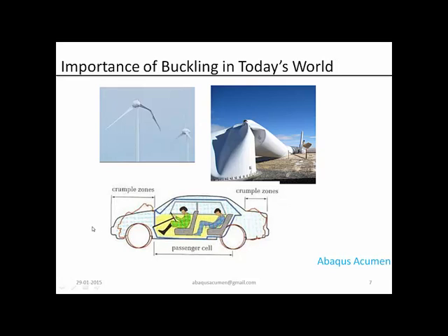So in a frontal impact, all the kinetic energy coming from the impact towards the occupant is mainly absorbed due to controlled buckling. And once you do controlled buckling in the crumple zone, the occupant is safe in a rigid cell, and that's what Mercedes-Benz used, the crumple zone concept, from controlled buckling.